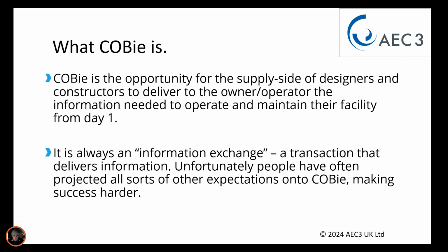I think because COBie was introduced along with a lot of pressure to adopt BIM and ISO 19650 or BS 1192 as it was then, many people have misunderstood COBie and think that it is BIM, or that it can meet other purposes other than handover. And that again has made it hard to be successful because there are a lot of things that COBie cannot do.